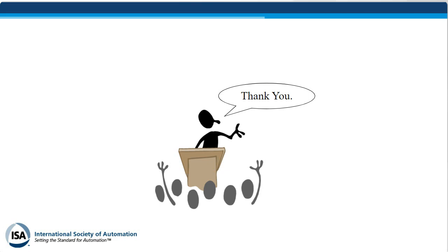One of the key activities for an operator is, number one, making sure that you adhere to the definition of alarm, that the operator has a specific response to the alarm, not just hit the acknowledge button. You'd be surprised how many alarms you can eliminate from a system or a plant when you do an alarm management project and adhere to the definition of alarm.